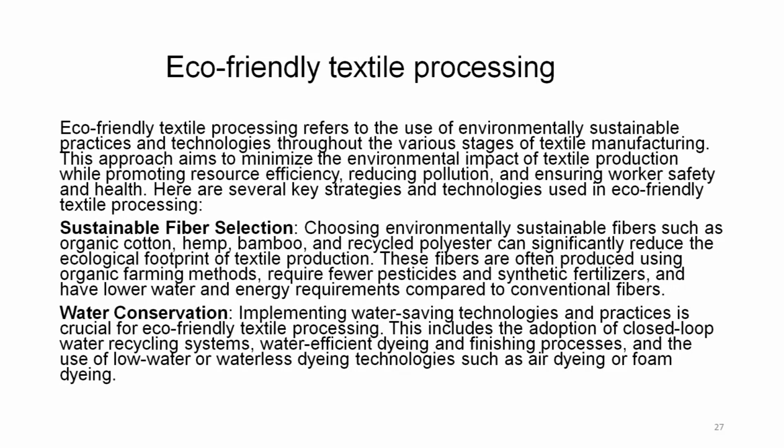Water conservation. Implementing water saving technologies and practices is crucial for eco-friendly textile processing. This includes the adoption of closed loop water recycling systems, water efficient dyeing and finishing processes, and the use of low water or waterless dyeing technologies such as air dyeing or foam dyeing, and even sometimes supercritical fluid dyeing.